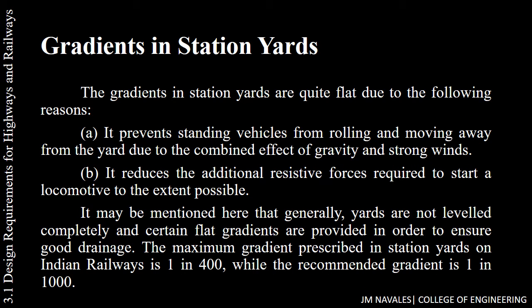Gradients in station yards. The gradients in station yards are quite flat due to the following reasons. Letter A, it prevents standing vehicles from rolling and moving away from the yard due to the combined effect of gravity and strong winds. And letter B, it reduces the additional resistive forces required to start a locomotive to the extent possible.